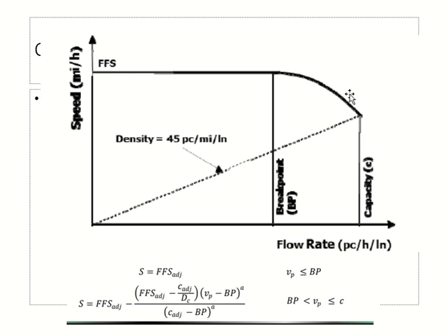After the break point the curve starts to decrease, and decreases rapidly, and it goes up to capacity, because after capacity there is no flow. After capacity you are going into level of service F. So this graph only deals with up to capacity. After capacity the graph does not look like this. It cannot continue like this.